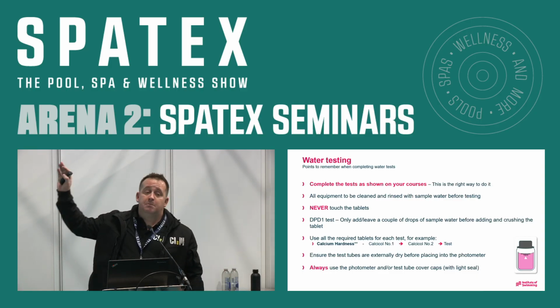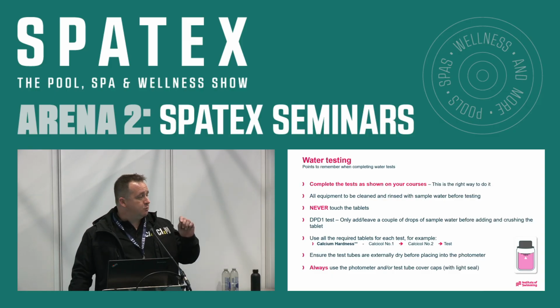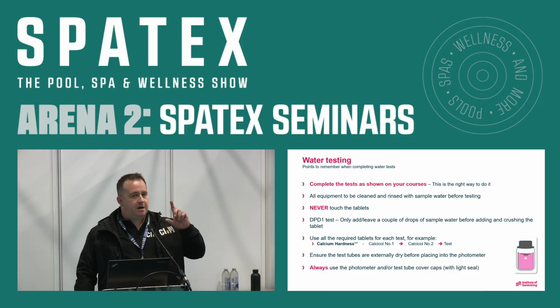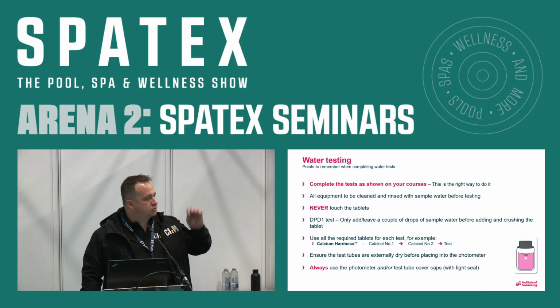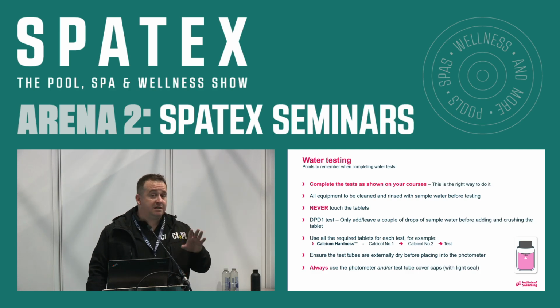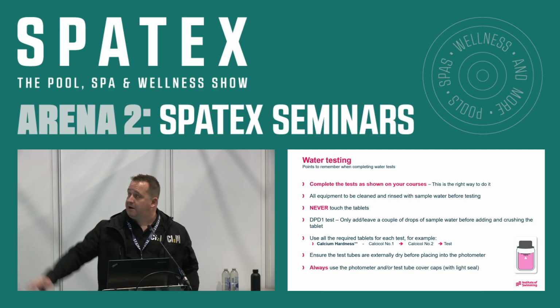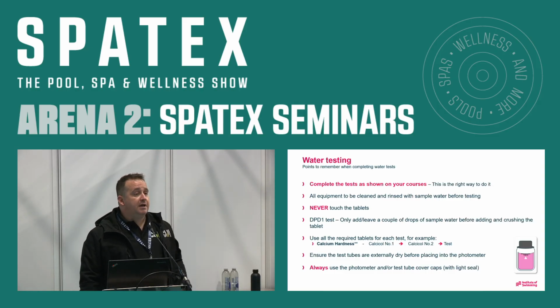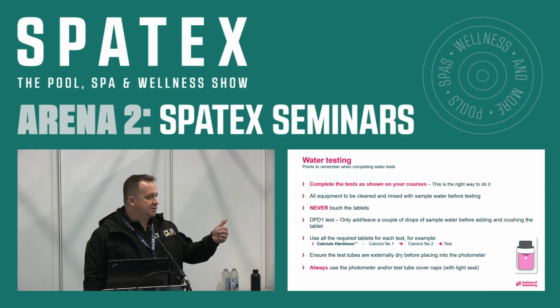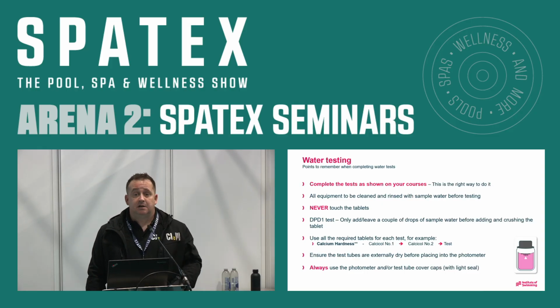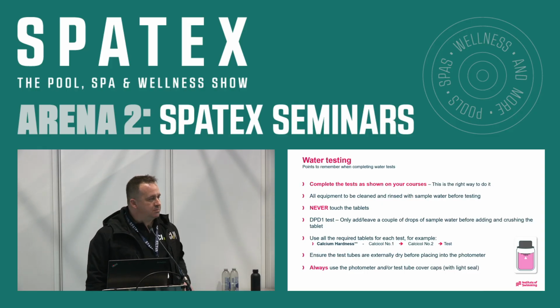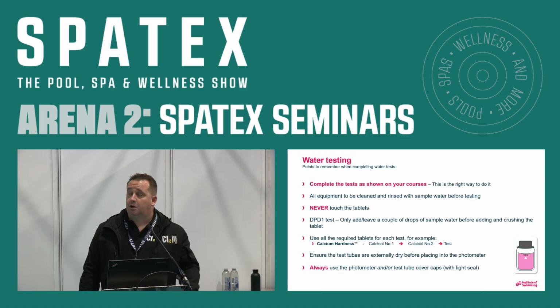Remember the DPD1 test? A few drops of water, crush, crush, crush, top it up. Don't drop your DPD1 test straight into 10 mil, otherwise you're going to get the bleaching out problem. All right. Certain tests require a wait time. So calcium hardness, for example. Any test that has 2 tablets going in requires a 2-minute wait. Your calcium hardness test, your DPD3 test, requires a 2-minute wait. Again, check the instruction manual of your units, and you can't go wrong.